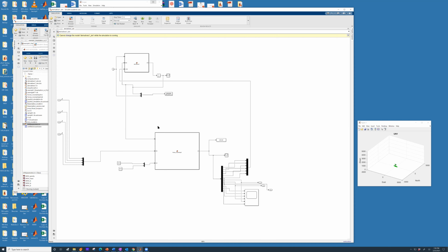The first, 5.1, is make yourself familiar with trim and Lin Mode. Second part is copy and rename your current Simulink diagram to trim. So this is the diagram that you should be using. The only difference is your UAV parameters will be corresponding to your Zagi plane, and the Zagi plane does not have a rudder. Zagi plane only has elevons.